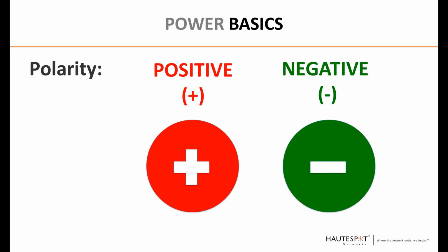Our PoE charge controller in these remote power system kits have reverse polarity protection. However, other devices may not have that, such as your IP camera or NVR. So you want to get the connections right the first time so you don't damage these products.